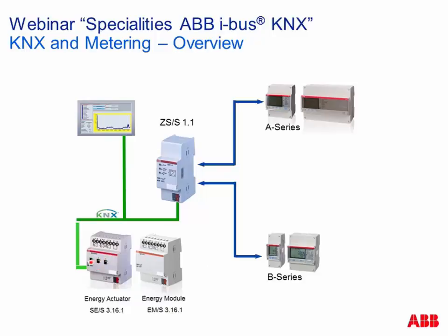Additionally, we have an intermediate meter, and so for example we can measure the energy from switching the light on, which is connected to channel A, up to switching off the light. So now in the morning when you switch on the light and you leave your office in the evening, you can see your used energy maybe here on your Comfort Touch or on another system. So for measuring the energy without switching, we can use the energy module.